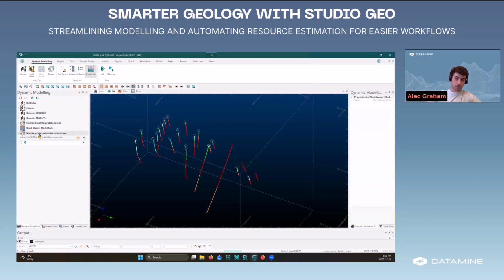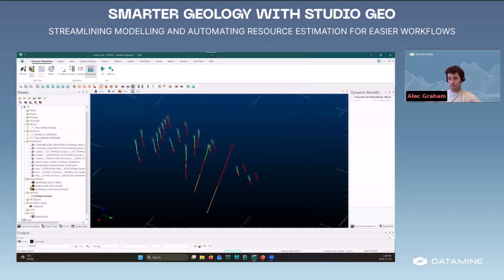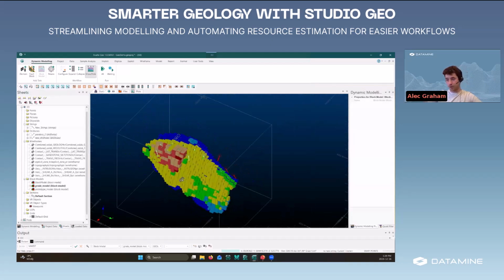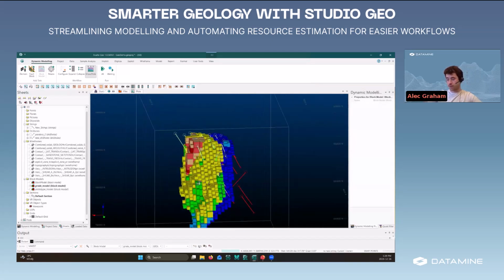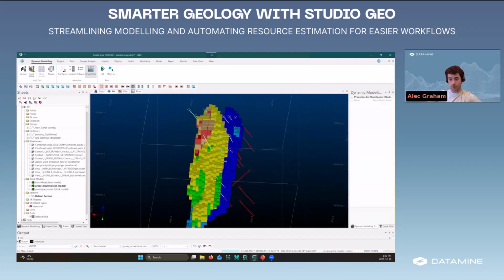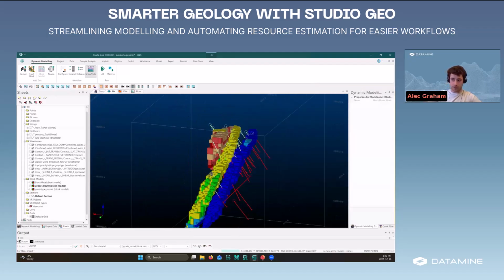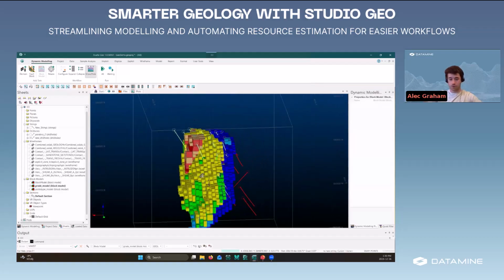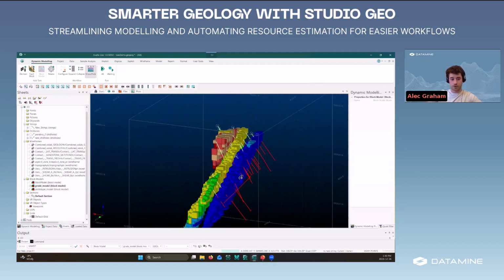And then we also have our grade estimation macro here. We're running a simple grade estimation on, I believe, copper, arsenic, and silver for this data set. And that will create our grade model for us. So I just have it set from cold to hot colors for copper grade, and I'm only displaying our 3 mineralized domains right now, those 2 shears and the intrusion.